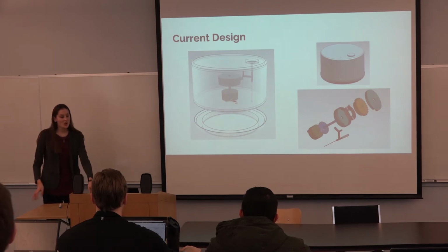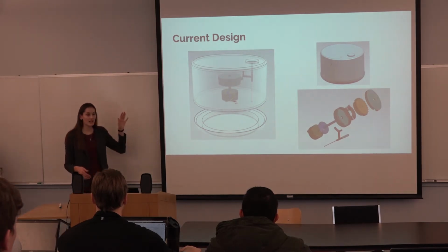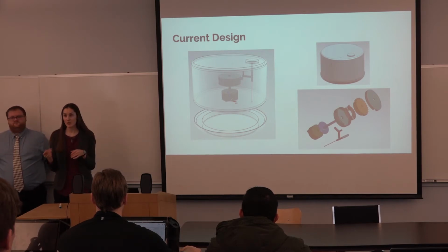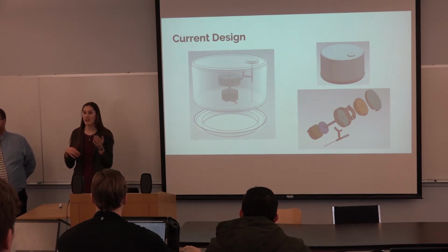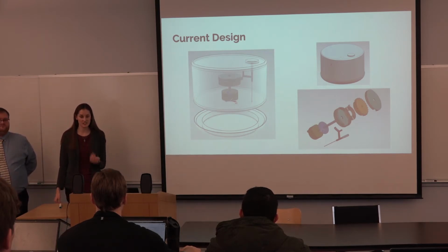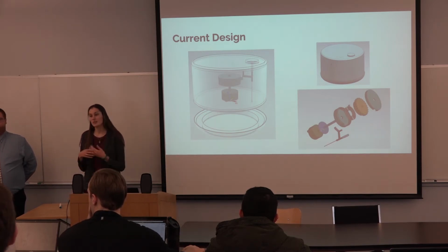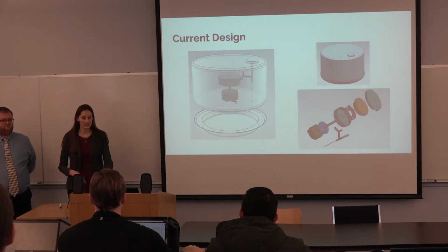So these images give an overview of what our final auto-injector will look like. The patient will press a button on the exterior of the device, and the needle will be inserted. The rotor will be allowed to spin, causing the drug to be pushed out of a chamber through the needle and into the patient's muscle tissue. The majority of our materials are 3D printed, and we'll also be using metal springs as the major components of our design.